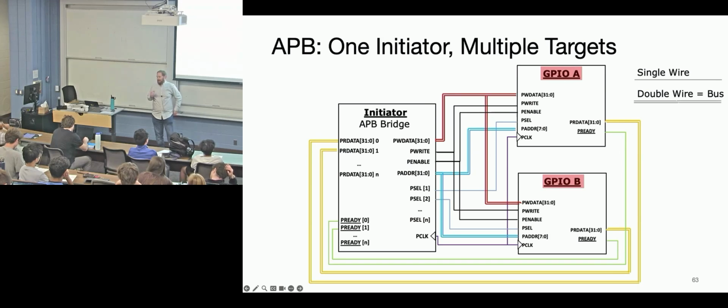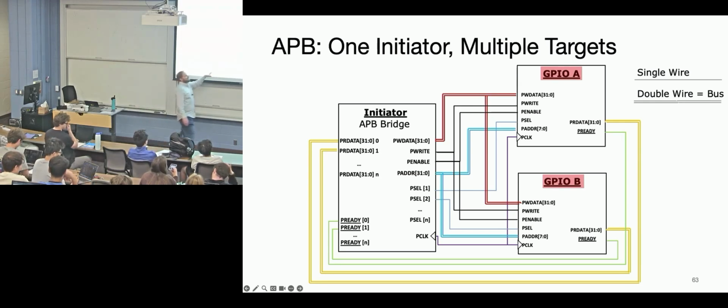So on those problems, if there's an address, would we have to write P-address to anything if there's only one register? If we just wrote P-select? Yeah, you probably want to look at the problem definition. If the problem definition said, hey, this is one block of a multi-block peripheral, and you have to worry about masking for addresses, then that would make a difference. But if we were vague and just said, hey, you're making a peripheral, and there's only one address in there, then P-select is going to do the selection for you. So think about P-select as selecting the global set of addresses, and then the address does the individual addresses inside that global selection. So it's kind of these two stages.